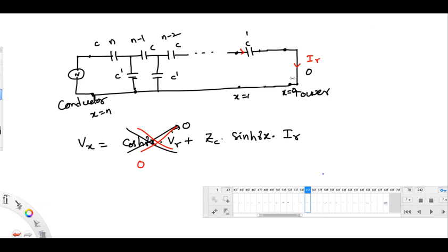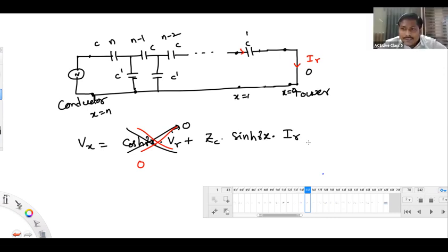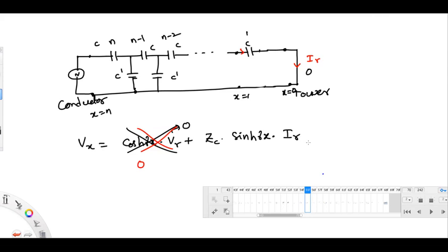Tell me, Imtiaz. Sir, I have a doubt in power factor correction. We are using the shunt capacitor for power factor correction, for increasing the voltage, irrespective of the voltage, no, sir? Which device will we use, sir? Shunt capacitor or synchronous condenser or any other shunt device? Practically, we are using shunt capacitors only to improve the power factor. Sir, but if we get the over voltage, then also we can increase that voltage, no, sir?